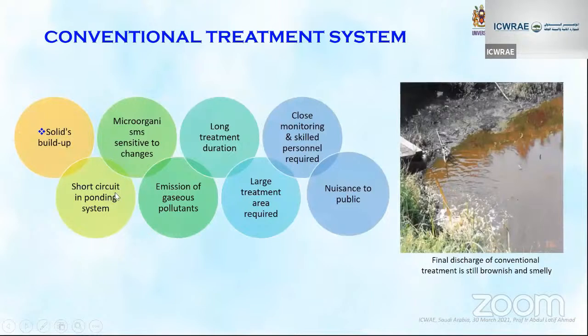Solid build up, short circuit of the ponding system, microorganisms sensitive to the changes, emission of gas, biogas, mostly methane and ethane, long treatment of 3 months, large treatment area, close monitoring, and it requires skilled personnel. It is also a nuisance to the public because it's smelly.